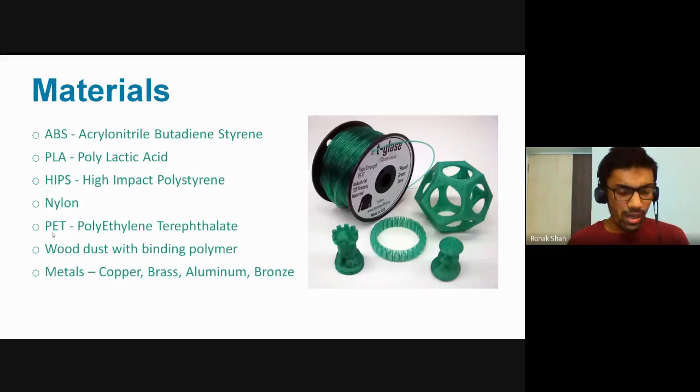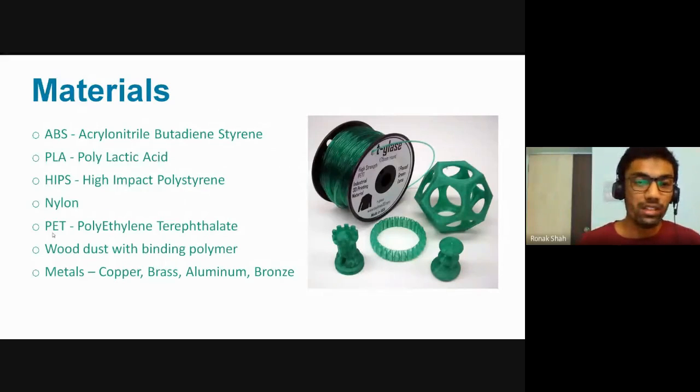And another advantage of PET is that it shrinks a little at a higher temperature. So you need to fuse this material at around 200 to 220 degrees, and during that phase the shrinkage of the material is very little. And again, these are flexible materials.